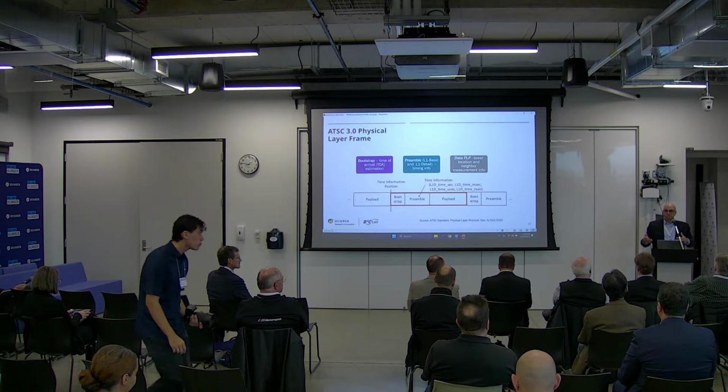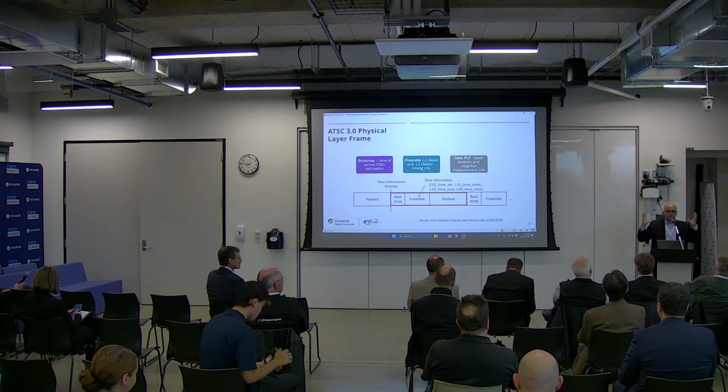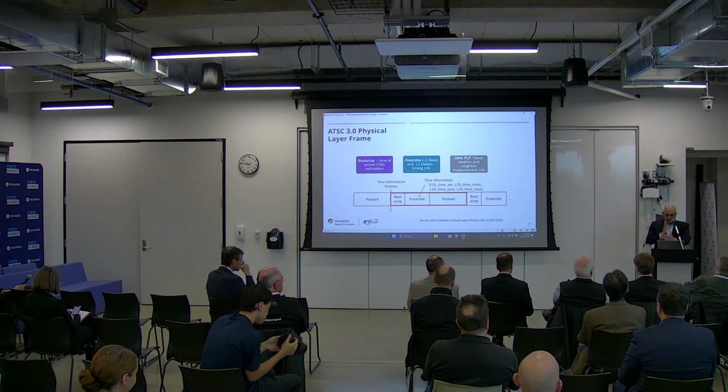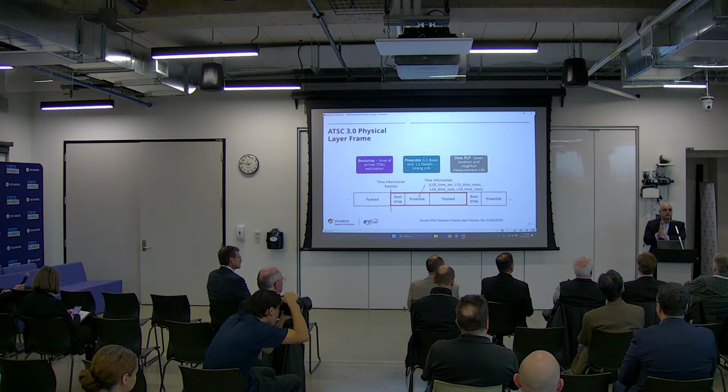You could use the ambiguity function. There are known signal processing and implementation techniques to do that. So you correlate, and you find, okay, I see the bootstrap signal starting at this point. And if you're timestamping the RF samples, now you have a time.